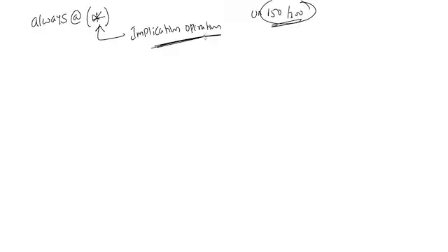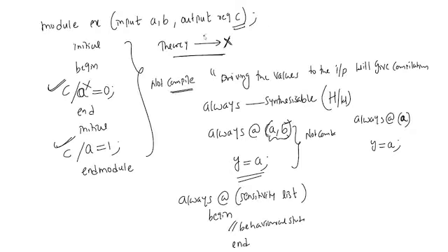So this part I did not understand completely. When you say if there is a change in the input, there is a change in the output, and that I need to give in the sensitivity list. Does it mean that, for example, in my code all the inputs are used, but some of them may not cause the output to change? Then I will not use them here, something like that? Means you need to indicate all the inputs only.